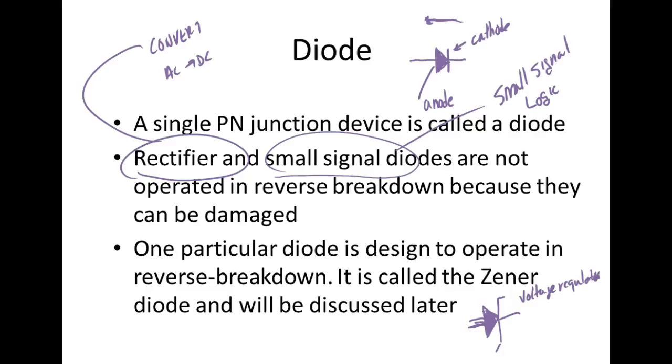Crank your car and look at the output of your alternator and turn your lights on. Odds are it's not going to change hardly anything, because that is what? That's regulated. We'll get into regulation a little bit. The Zener is the main diode that sets the reference for regulators.